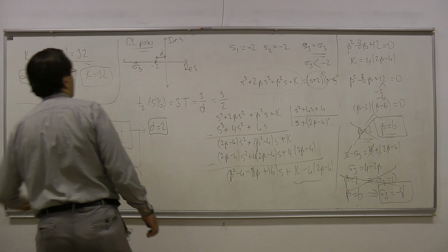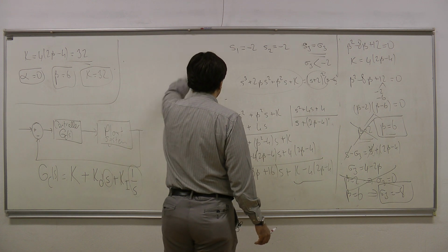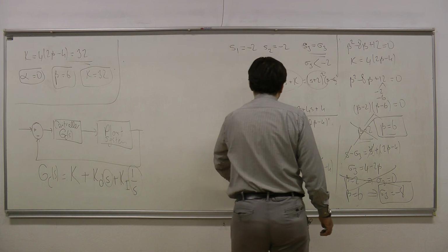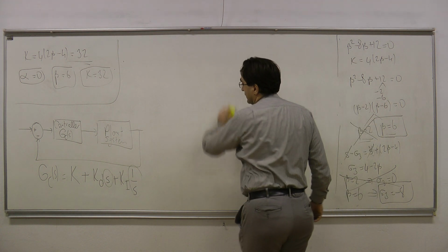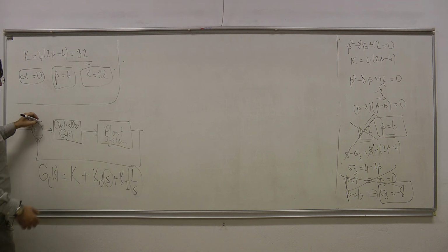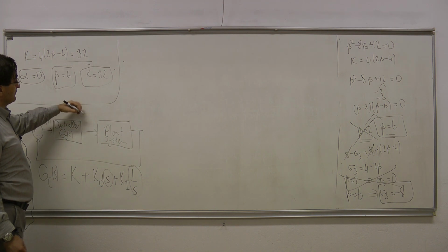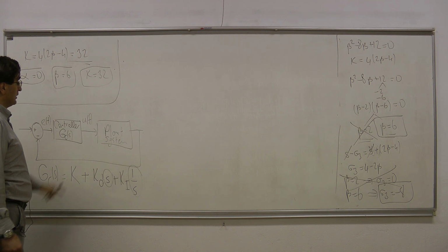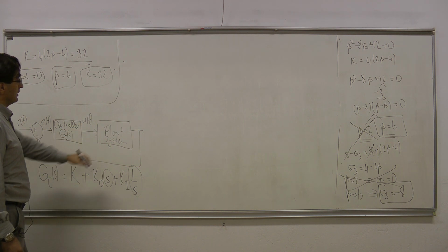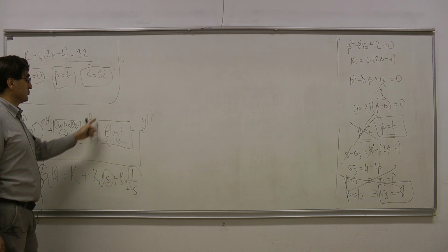So what does this mean for the controller? I can actually try to write what the input and the output of the controller system would be. Okay? The input of the controller is usually the error signal. This E of t enters as the input to the controller, and the output of the controller is the input to the system, which is U of t. This is the reference signal R of t, and this is my output Y of t. So that is the system to be controlled.